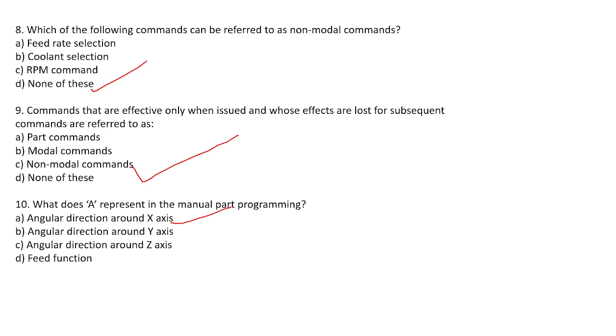For producing those dimensions, sometimes you need to provide coolant, or turn the spindle on or off, or change the tools. For those operations, M code commands are given.